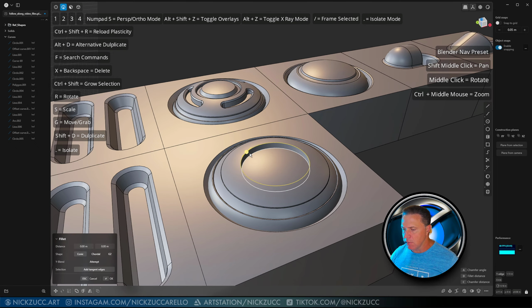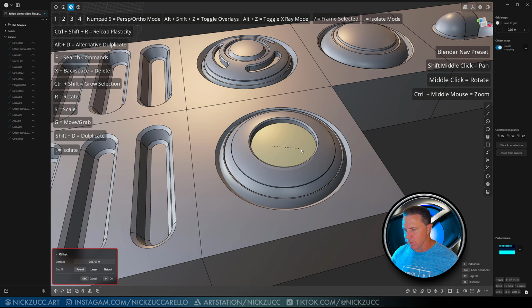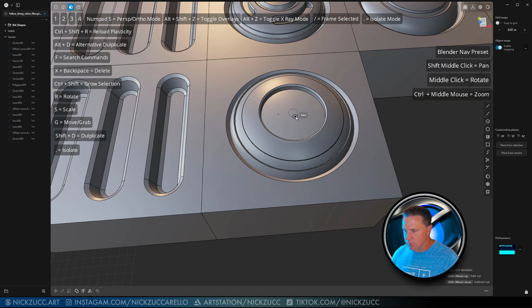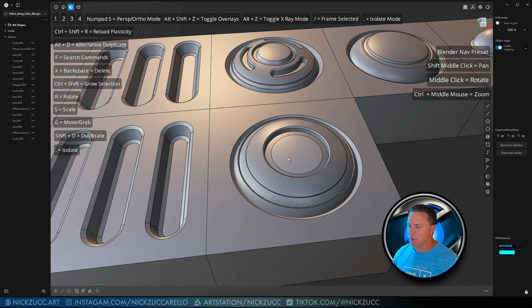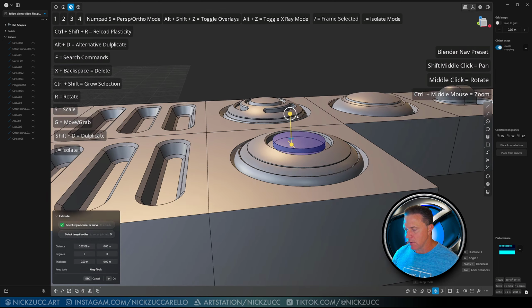So let's tap 2, and let's drag in like this here. I'll select 3 and then do O for offset on this part. Let's select 3 again. Let's try that again. O. And it's not behaving for me. So let's try Control R. It'll let us do that. Okay, so I'm just going to do Control R to get this part and this piece. I'll select this, tap E for extrude, extrude that up.